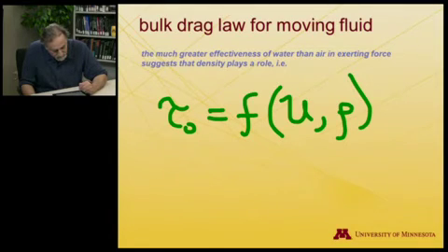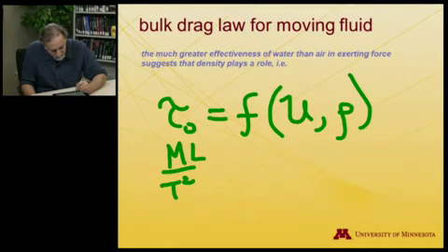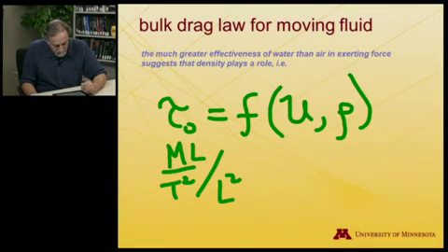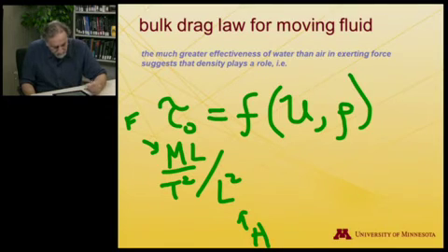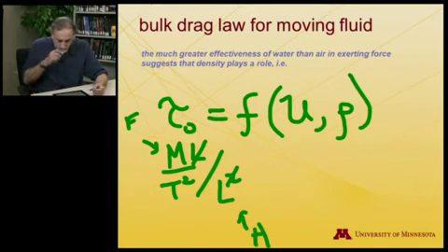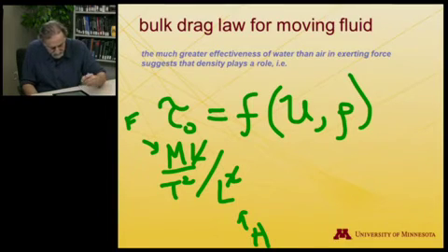The units of stress are force, so that's mass times length per time squared, mass times acceleration, and then normalized by area. So force per unit area, and this has mass. We can cancel the length here, and we can cancel that square, time squared, and then a length on the bottom. So these would be the Pascal units that we've been talking about.